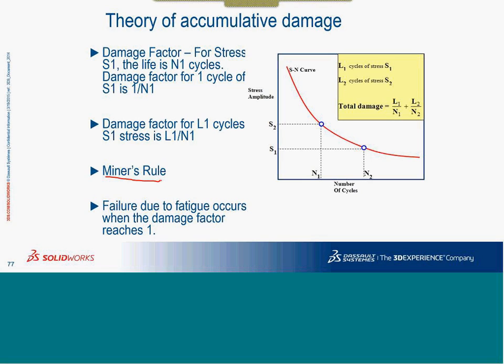Or the other way around, if we see practically, the expectation is that after application of a load for a certain number of cycles, there is an amount of damage, and thereon one more load comes up, and there is a kind of order when we have these multiple loads working on a shaft or any product. Whereas we are doing it using Miner's rule, the order in which these loads are applied does not have too much significance. It is simply added. So for all practical purposes, this is accepted. This is the way it works, and it's also okay to assume it.